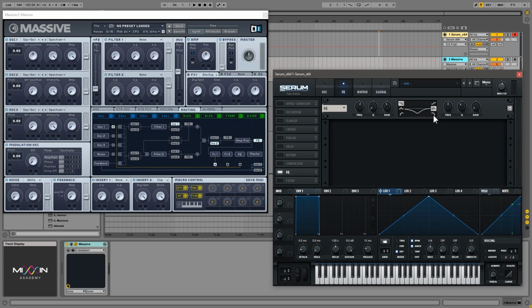We also can turn these into cut filters. So the one on the right is going to be a high cut filter or a low pass filter. If you remember, they have two definitions. It's cutting the high frequencies or, in the same sense, letting the low frequencies pass. So we have a high cut filter or a low cut filter. A low cut or a high pass, in the same logic, is cutting the low frequencies and letting the high frequencies pass.